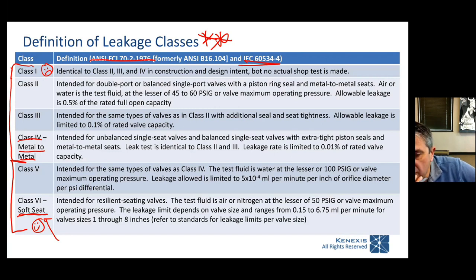But in a refinery, the fuel gas is usually a collection of junk collected from other process units that's going to contain a lot of salts, chlorides, fluorides, acids, ammonia, all kinds of particulates, coke. And when that gas goes through these valves and the valve moves, you start basically sanding the surfaces using those contaminants in the fuel.